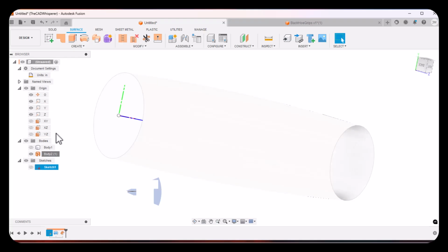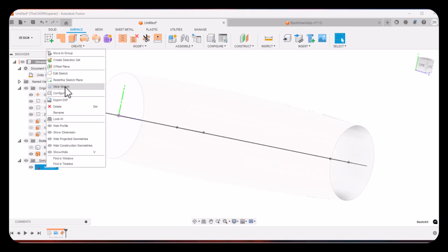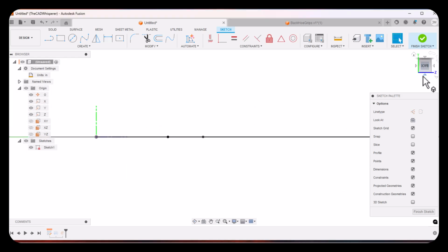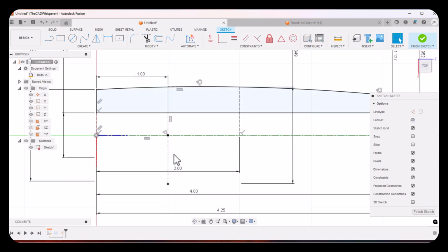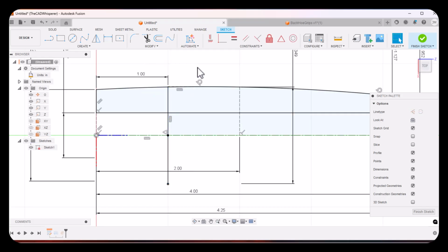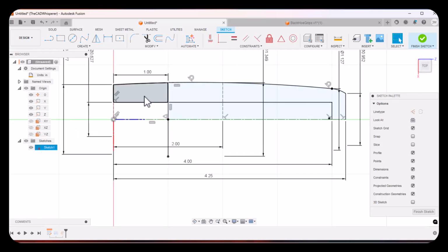I'm then going to edit that sketch, and we could have done this originally, but I'm going to edit that sketch and I'll go in here and I'm going to change that construction line to an object line. So I'll change this to a normal object line. And the only difference is if before when we did that revolve, we would have had to pick this area and this area as 2 steps rather than as 1 step. But I just wanted to keep that simple when we did that revolve.